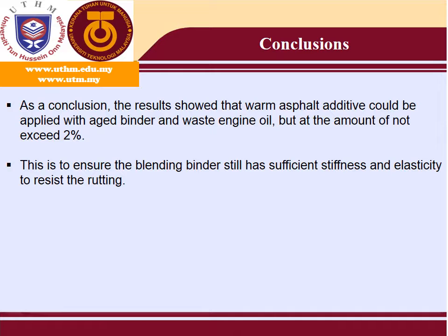As a conclusion, the results show that warm asphalt additive could be applied with aged binder containing waste engine oil, but at an amount not exceeding 2%. This is to ensure the blended binder still has sufficient stiffness and elasticity to resist rutting.